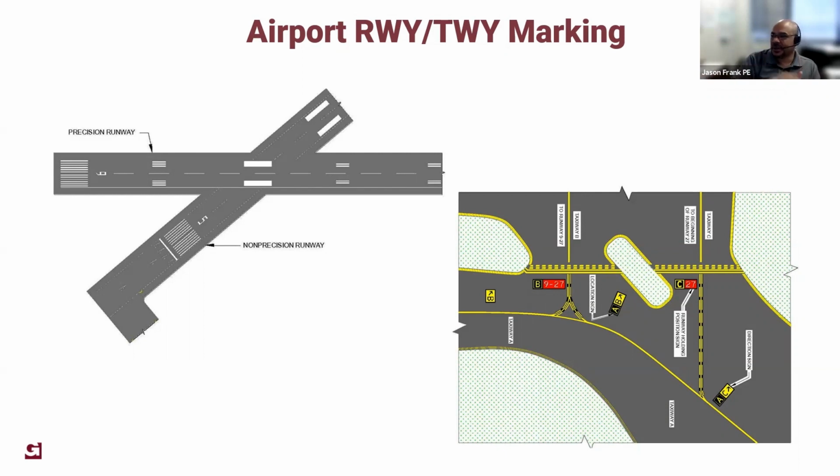On taxiways, it's all in yellow marking, and you can also have signage that's painted on the surface. Anything that has a red background with white numerals is usually just like us. It's a stop. Can't go any further without permission. Anything with a black background with yellow numerals is a location. Anything on a yellow background with black numerals is a direction.